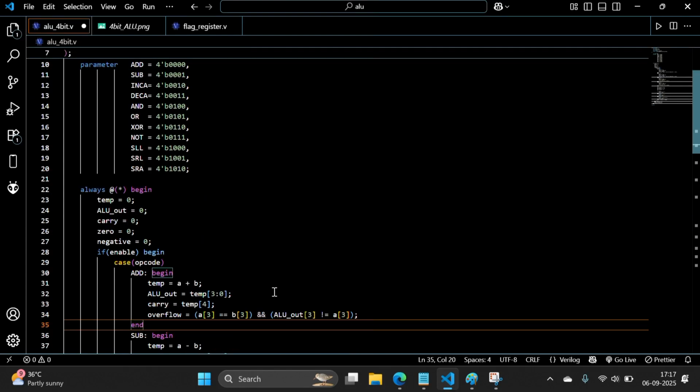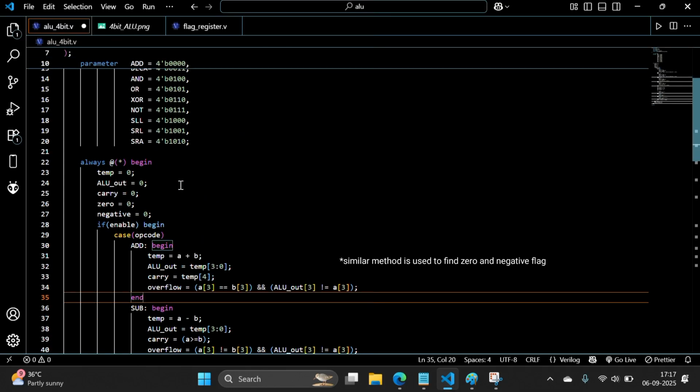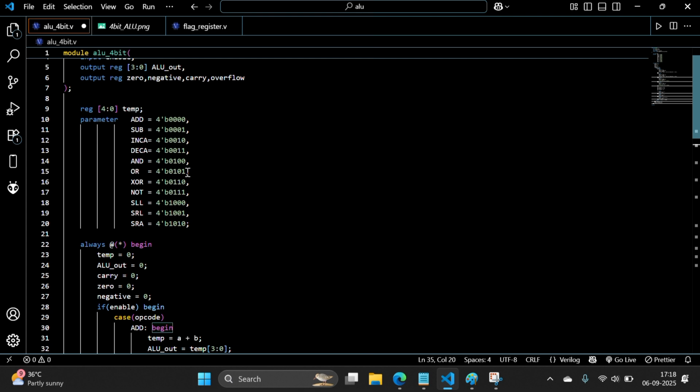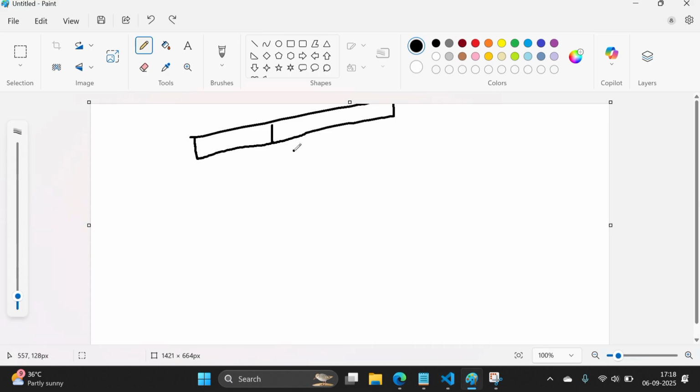So this is a simple code. We will be performing an operation based on the opcode given in the data. This opcode is nothing but the instruction that came with the instruction set. For example, the instruction set will be like this, and the first part from 31 to 26, the opcode, will basically be 6-bit, but we are using a 4-bit ALU and we are providing a 4-bit opcode. But in a real scenario, like in MIPS32 processors, you will be having an opcode of 6-bit.